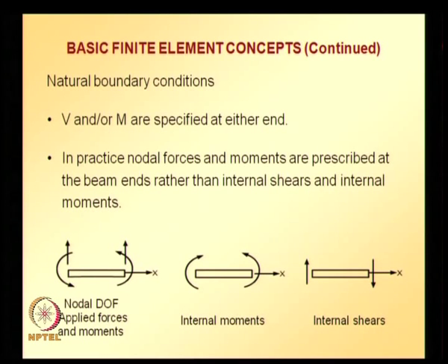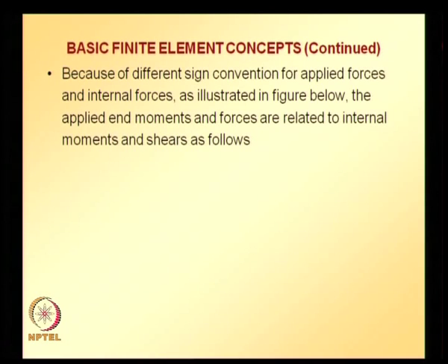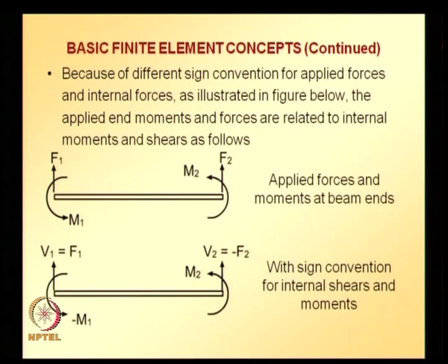So, noting these relations between internal moments, internal shears and applied forces and moments, because of the different sign conventions, as illustrated in the figure below, the applied end moments and forces are related to internal moments and shears as follows.